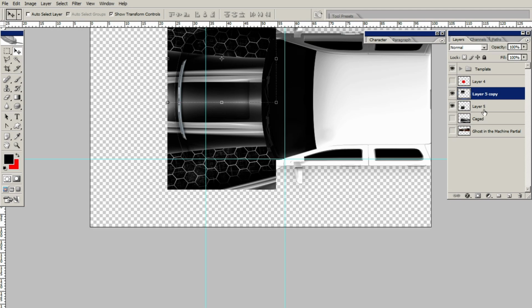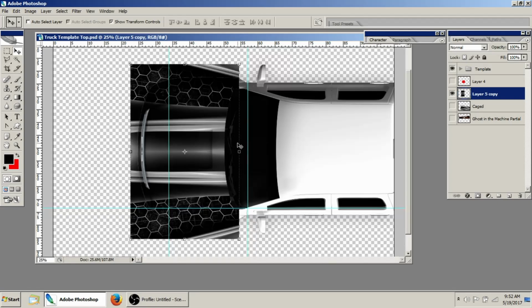If you wanted to check this, you just go ahead and drag it back onto your template, and remember to rotate it back to the exact same angle. If you wanted to write that down, just to double check yourself to make sure that's going to line up fine. But this should be a perfectly mirrored section right here when it meets at the hood splice.